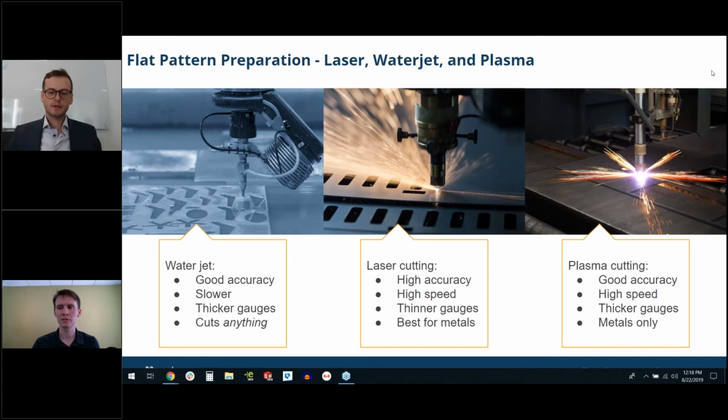processes. Laser cutting, probably the most common process that you're seeing right now, is because it's extremely high accuracy. The cost of fiber lasers has really come down and the speed has gone up. So those are extremely highly accurate hole-to-hole, feature-to-feature, very fast. So we can cut 16th inch steel at 1,000 inches a minute, just for reference, right? So it's wild to watch. It's pretty fast. Yeah. Like the head moves so quickly, it would scare you the first time you see it.